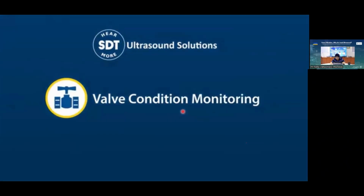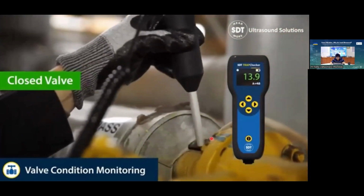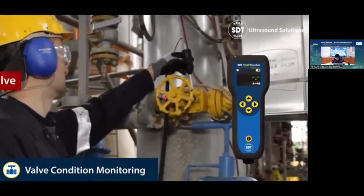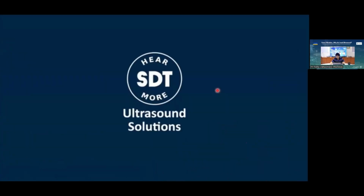This is a video of how to inspect the valve condition. When you measure the sound before closing the valve, it's a good condition, and the decibel should be the same. But when you measure the sound after closing the valve, the decibel goes high. You will know that if you close the valve 100%, there should be no flow in the upstream or downstream. If you measure the sound from the inlet and outlet, it should be the same.